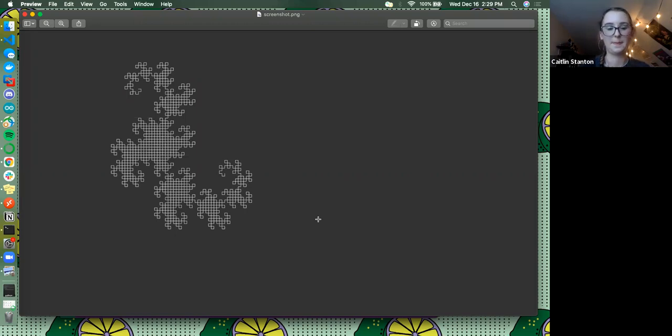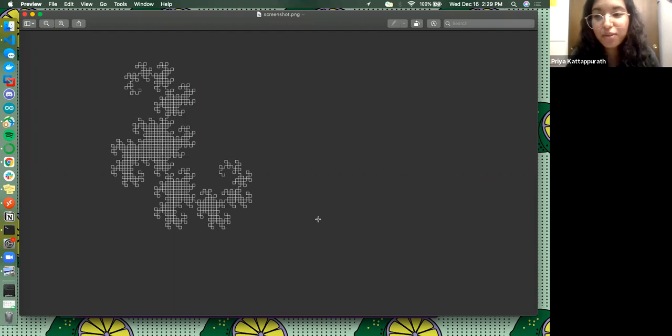Why did you choose 8 M10K blocks instead of, say, 16? Oh, we actually do have a reason for that. You might have noticed when we were doing the serial input, we were able to go directly into the next LSystem. That's because we're clearing the M10Ks at the beginning of the rules FSM, or create system FSM. And the bigger the M10K or the dual RAM ports are, the longer that takes.